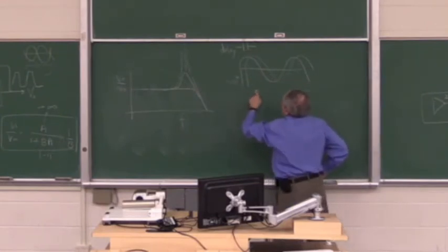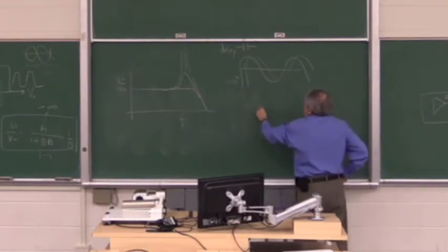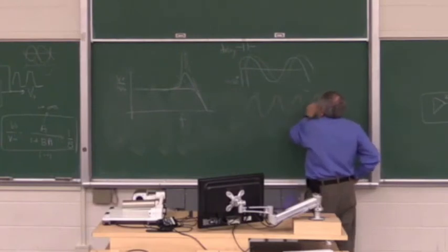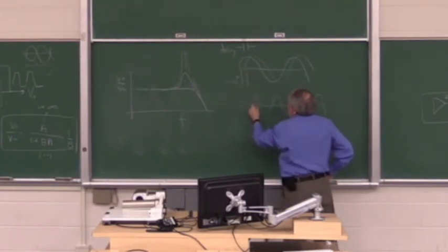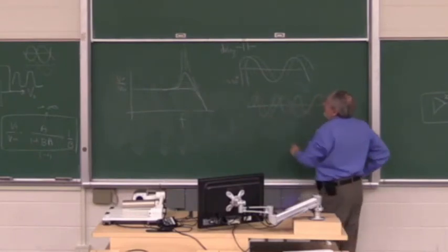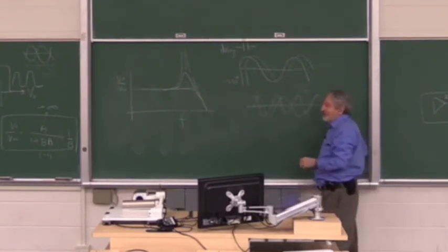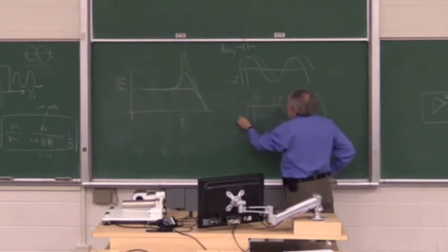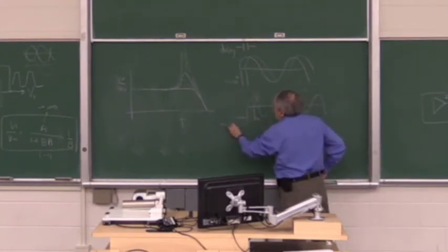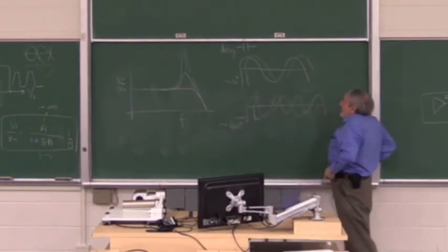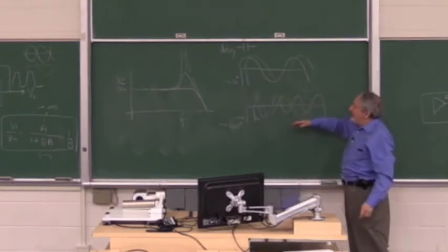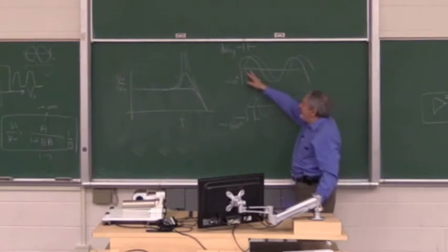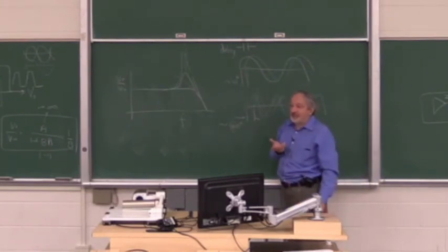But if that sine wave is twice the frequency, the same delay, exactly the same delay, now will give you a bigger phase shift. Right? If the frequency of the sine wave doubles, the same delay now, let's say, gives me 60 degrees phase shift. And if the frequency of the sine wave goes up and up and up, at some point the same delay will give me 180 degrees phase shift.